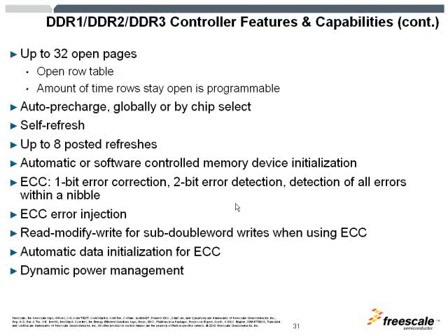Self-refresh, which is to maintain the DDR content while you are either going into a power management mode or you're powering down on the controller side, is available. Up to 8 posted refreshes are available. The automatic or software controlled memory device initialization is also available.